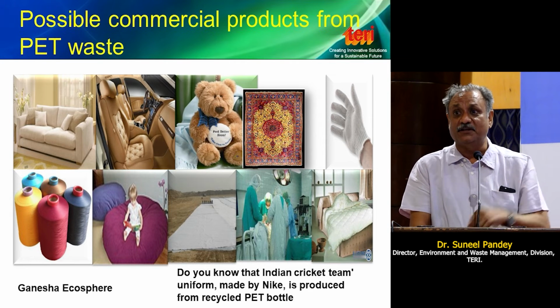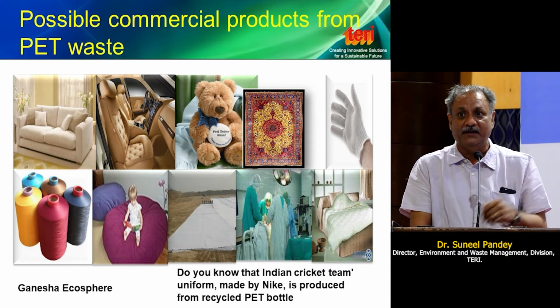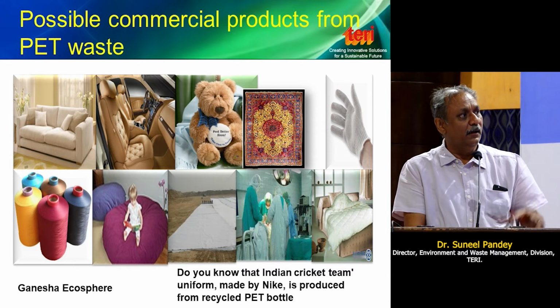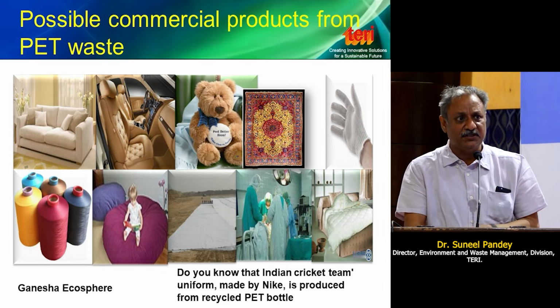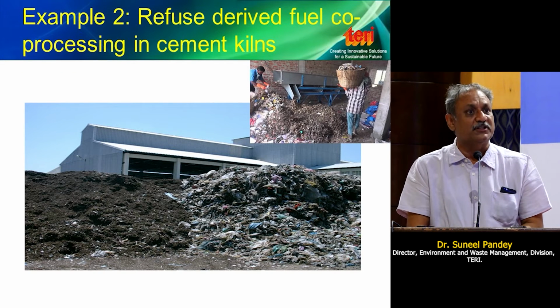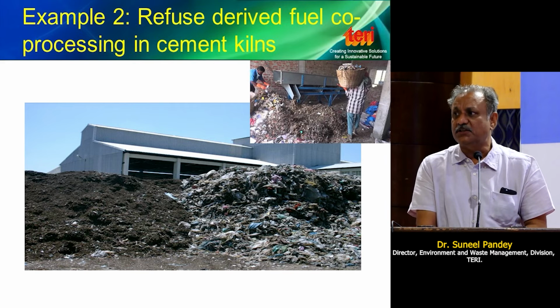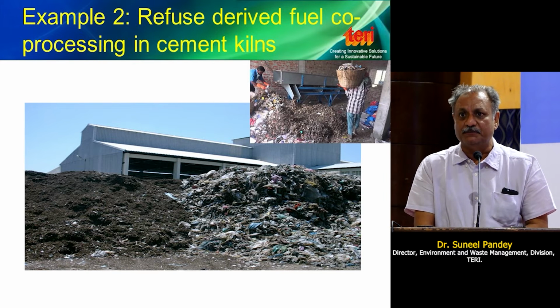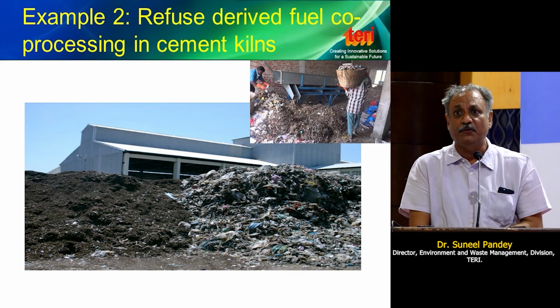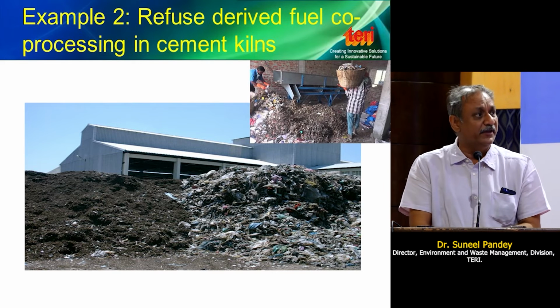Till waste segregation is better and improved, and composting is done only on segregated waste at a larger scale, these can be pre-processed, cleaned, shredded and produced into something which looks like this. This is what we call fuel pellets. In solid waste management terms, I'll call it refuse-derived fuel, which is derived from waste.